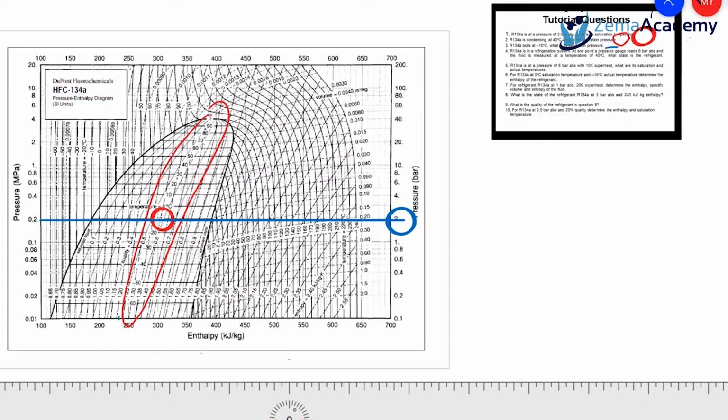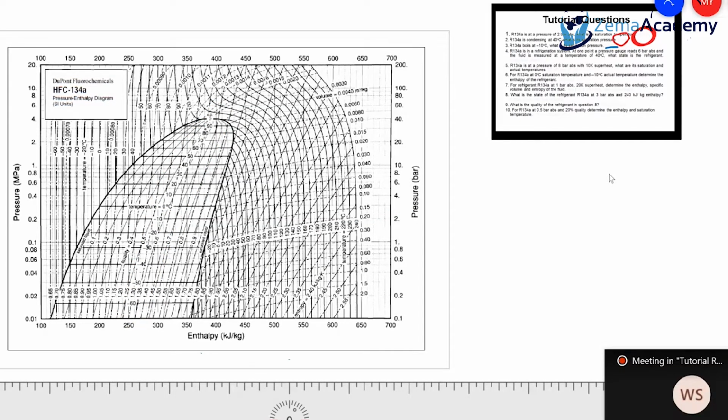I think that and question 1 are the same question, though. The other way around, yes. In the other one, I gave you the pressure where you had to read the temperature, but here I gave you the temperature where you have to read back the pressure. So it's just to show the correlation between your suction temperature and suction pressure. Either way, if you know one of the parameters, you can directly know the other. So throughout, we're using the same refrigerant, R134A.